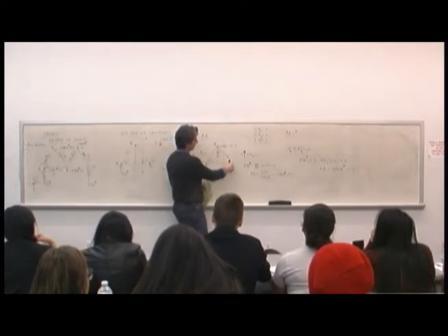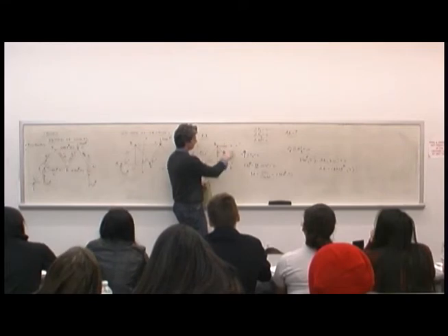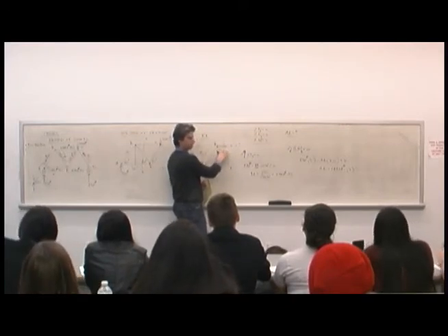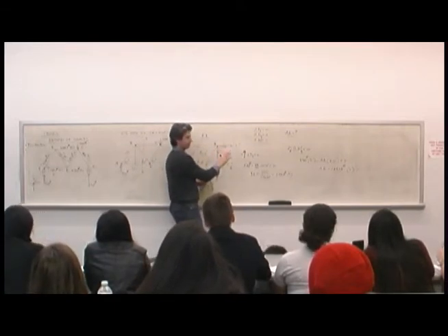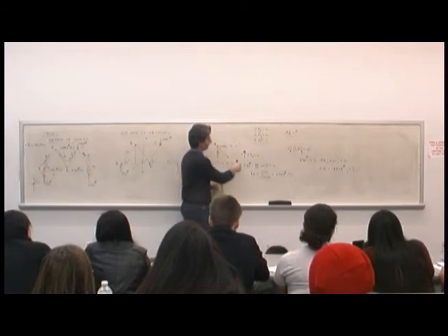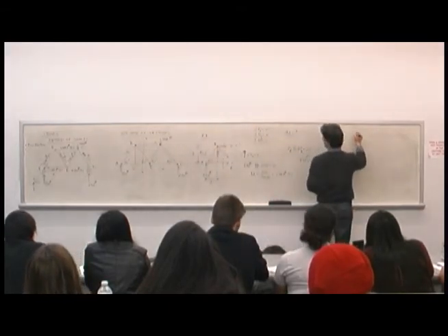If I put myself at E, I take this force out of the equation, I take this diagonal force out of the equation, I'm just left with this and this again. So I can solve for BC. That might be easier than balancing everything in the x direction by taking a component. You can do that, that's fine, and it would work and get the answer. But let's take moments about E. And we're looking for BC.